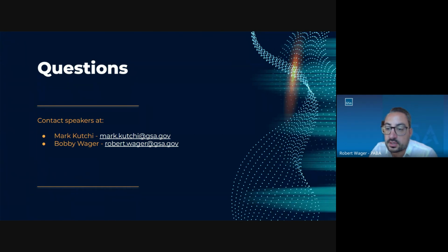Thanks for a great session. Can you talk a little about wildfire smoke migration and what it means for building occupancy? So, Ann, I touched upon this earlier in the presentation regarding our updated requirements for wildfire risk management, and how we now have a requirement for air handling equipment that interfaces or handles outdoor air to provision for an extra filter section so that carbon filtration can be slotted in.